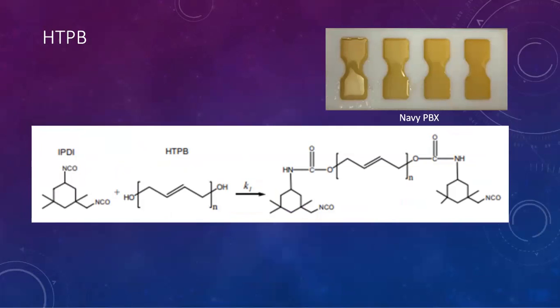hydroxy-terminated polybutadiene, actually comes as kind of a really viscous, sticky goo. So to make samples and how they cure it, you add IPDI to cure it and put it in an oven for about a week. And we generated and made these molds to give us dog bone shape samples so that we could also do mechanical testing like we had done on our aluminum.